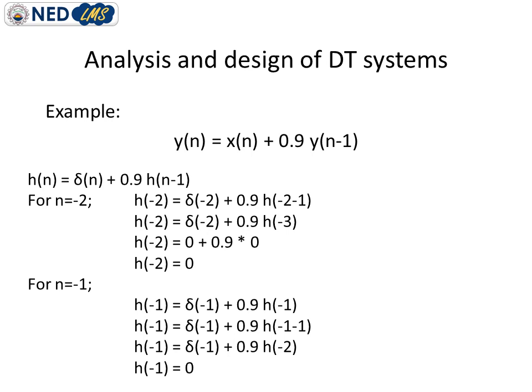For example, if we are considering n is equal to -2, then actually we have to put the value of impulse response at the previous time instant, which is the feedback value. And we know that the impulse function exists only at n is equal to 0. So there is no impulse function before, so the value before this time instant is 0, because there is no impulse, so there is no impulse response. So in this way, impulse response at n is equal to -3 is 0. And again impulse function at -2 is again 0. So overall the impulse response at n is equal to -2 is 0.